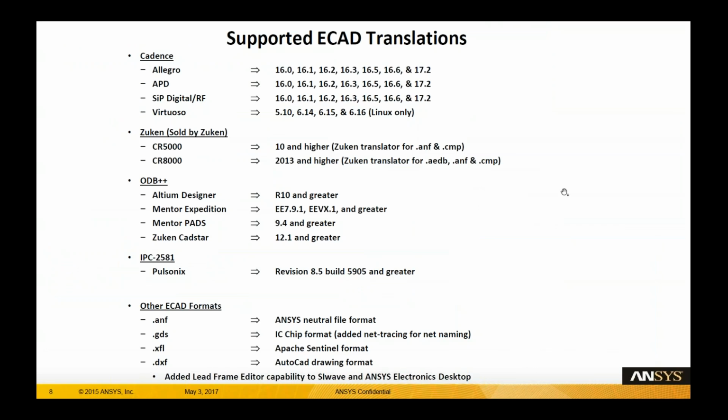SIwave supports pretty much all of the prevalent ECAD translations, from Cadence Allegro, APD, SIP Digital, Virtuoso, Zuken, ODB++, and also other general ECAD formats.